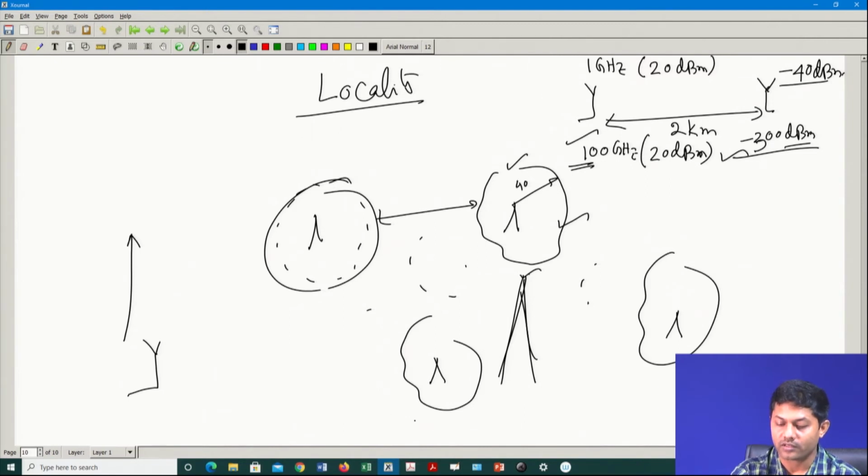So, that huge power will be lost unnecessarily in this whole area. But if I use a small base station targeting only a small area, the power will be much more optimized. And when I have an intention to serve a small locality, then why not go to the higher RF, because those RFs are anyway available spectrum, right? We just discussed that, because that is the whole reason I want to shift more and more: I want to increase my data rate, I want to come out of my congested region. Then I am facing the problem of this transmission power loss.